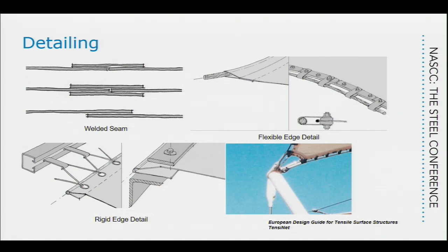You kind of weld those two things together, you fuse them. You fuse them along that whole overlap? Yes, right here it gets fused all through that seam. Typically about a 4 to 6 inch overlap is very typical of what you would see in most materials.